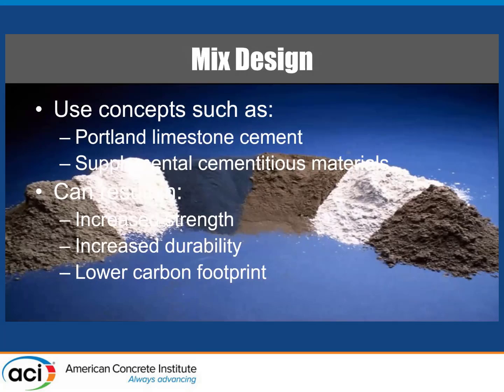Mix design, for new structures, is maybe the most important thing you can do to address a lot of issues, not just resilience, but sustainability as well. You can use concepts such as Portland limestone cement or other supplemental cementitious materials. Of course, there are other admixtures you can put in the mix design that will change the performance of the concrete and give you a more resilient or sustainable mix design. Obviously, you can increase the strength doing this. You can get increased durability, both of which lead directly to better resilience.